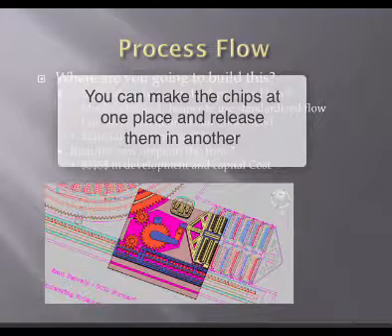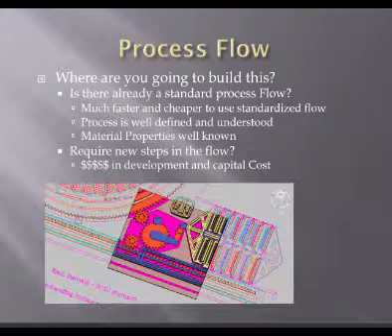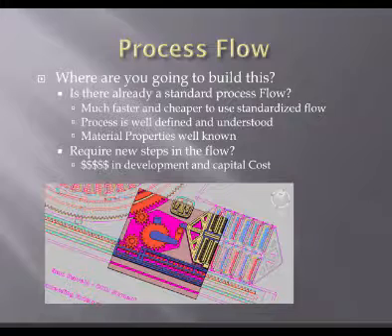If you submit a rudimentary design to somebody that's got a standard package that will fit in, I assume they're going to charge you a certain percentage. Yeah, but then you can package it yourself too, right? If it's a wire bond thing, you can actually buy the packages blank and then put your chip in it and hand wire bond it for your prototypes.